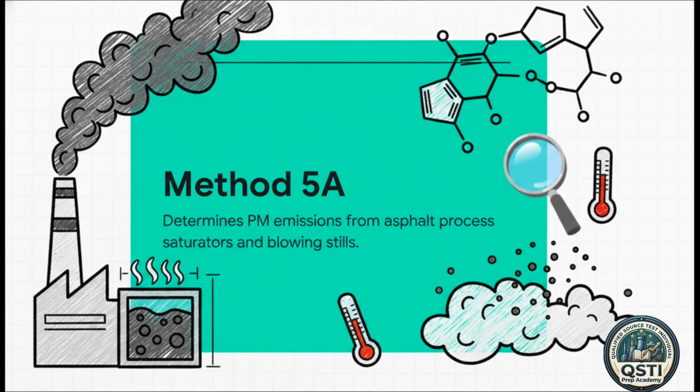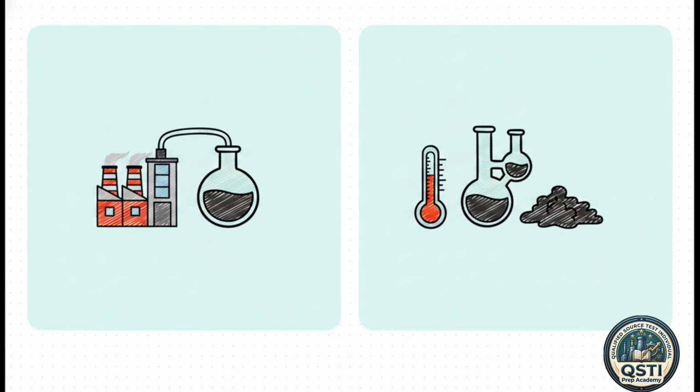The EPA recognized pretty quickly that a one-size-fits-all approach just wouldn't work here. If you use a standard test, you may completely miss the material that condenses at specific temperatures, or worse, you could absolutely ruin your equipment with asphalt residue. This method guarantees that the PM mass, which crucially includes any material that condenses at or above the filtration temperature, is captured accurately. Here's the crucial point.